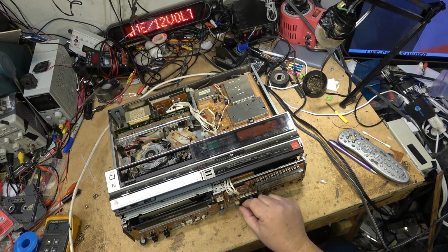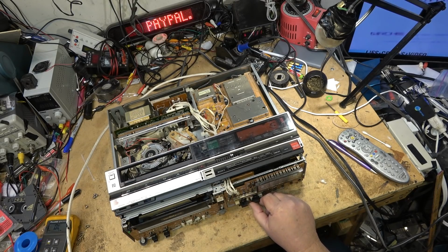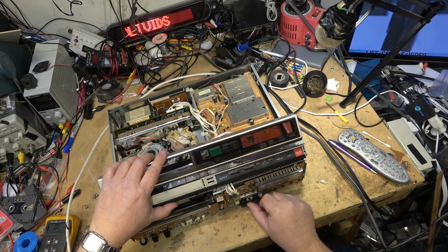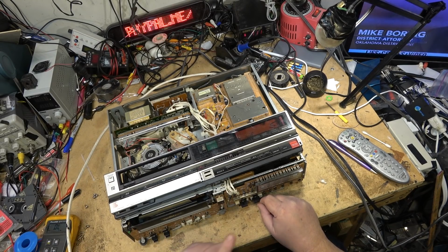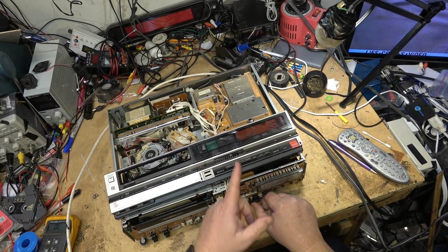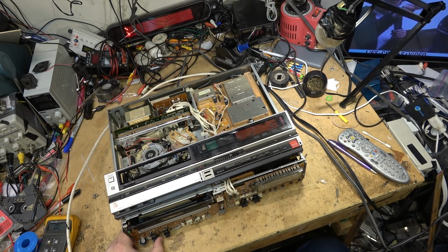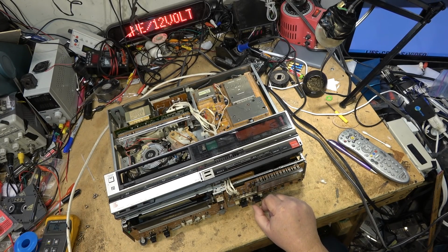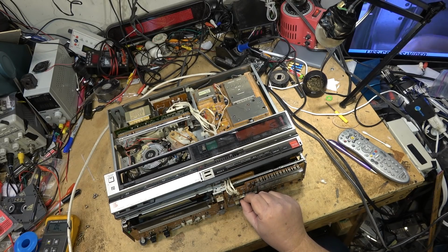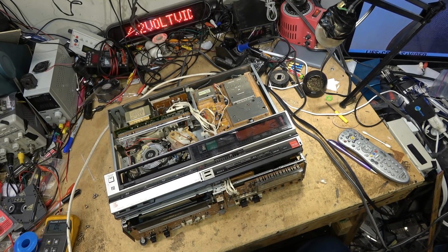If I switch my audio monitor over to mono, oh, there we go. That's the switch. It's this one. Normal. Okay. I think he just thought, in the hi-fi position, there's no sound because I'm in line audio, but the mono always records from the tuner. 18 years old. Panicked. And if I switch the other input back, right, so there's the hi-fi audio. There's the linear sound picked up. This control is also dirty, so we're going to give this control a shot of cleaner before I put it together.